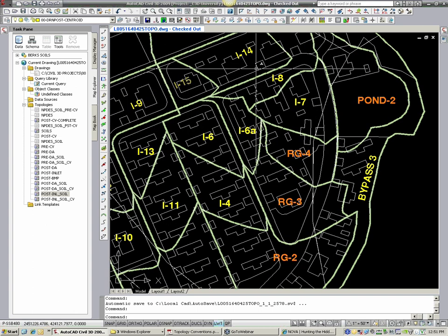And what I mean by that as well is these inlets maybe have a snout. They come down, so the snout takes out a certain percentage of contaminants. This rain garden takes out a certain percentage of contaminants. When I'm talking contaminants, I'm talking total suspended solids, total phosphates, total nitrates. Then this water goes into this one, and so on and so forth. So it's really a numbers game: you're taking the area, taking the contaminants, dividing by a percentage, going to the next one, adding, because as this is taking the load from this one, but now it has its own drainage area, so it has a different load, and it has to calculate all that out. Well, it's essentially the same procedures as we did today.